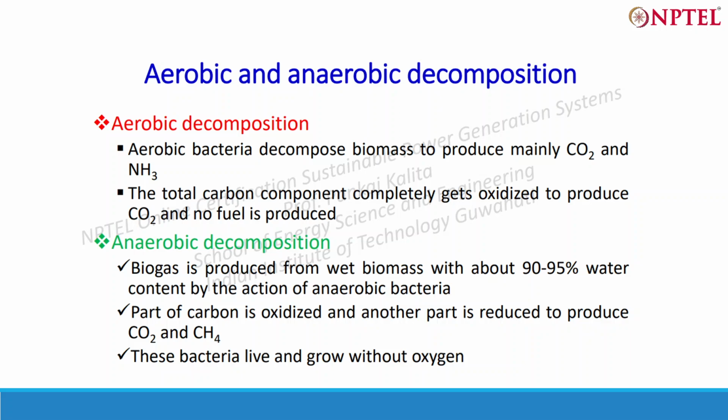So these are some of the criteria that have to be fulfilled when you are going for anaerobic or aerobic decomposition. Similar criteria exist for thermochemical conversion also. If you are going for thermochemical conversion, it should have a moisture content of less than 35% as per the Municipal Solid Waste Management Manual in India. But if you are going for higher quality RDF-1 type of components or waste, you have to go for less than 10% moisture.